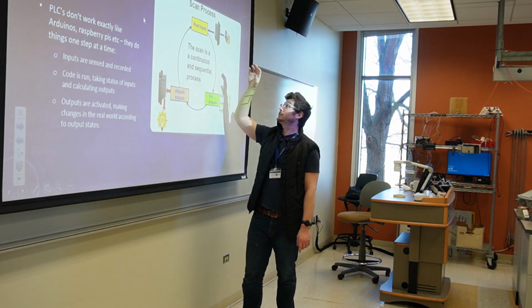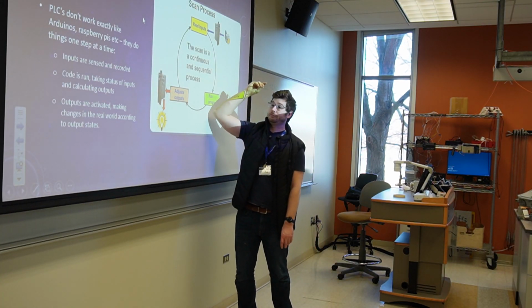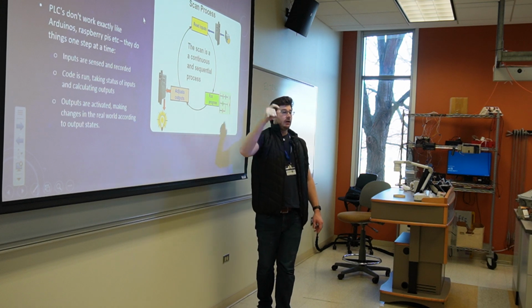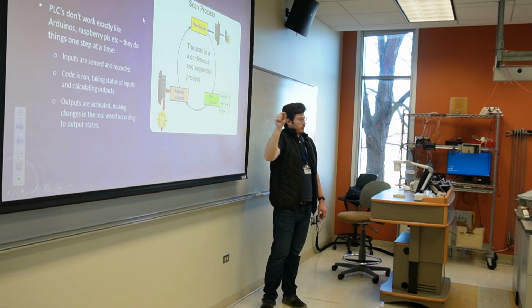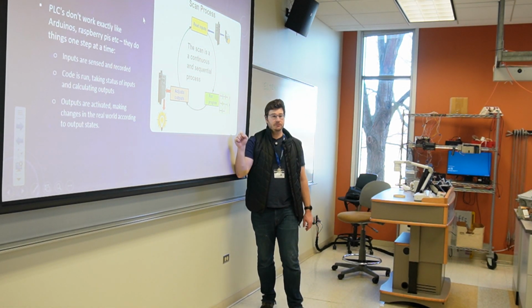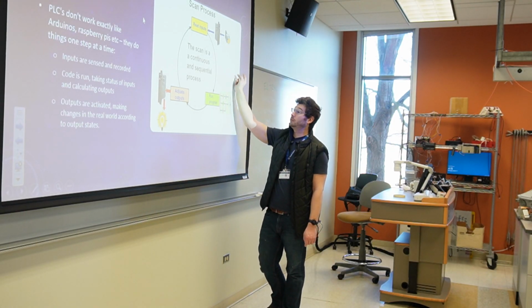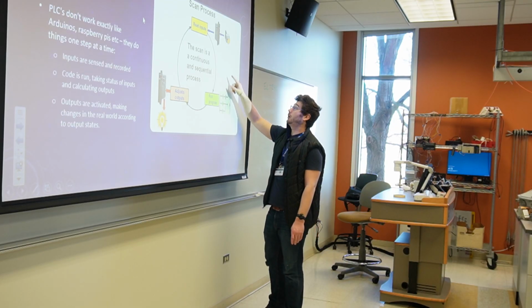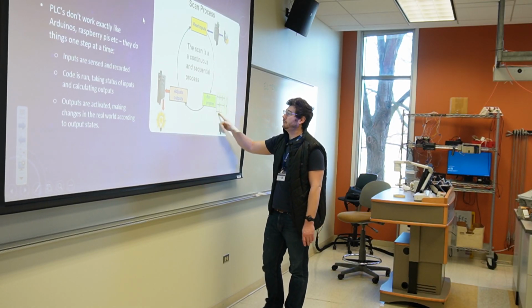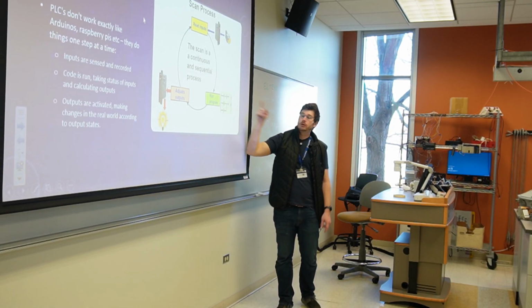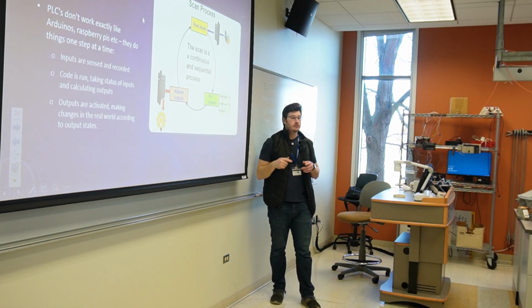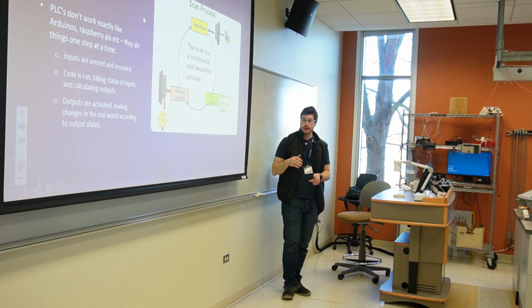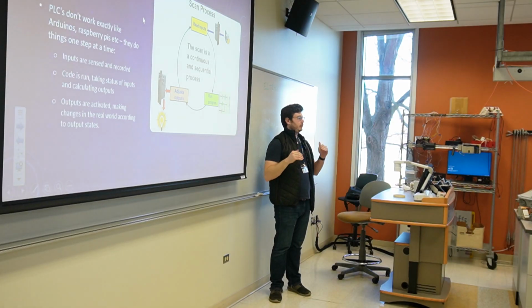Okay, so what happens is that the PLC will kind of freeze time. It'll go snap. What are all of my inputs at this current instant in time? It'll read it in almost instantly from I1 through I8, and it'll save that record. And then it'll pass that record, what are all of my inputs at this instant in time, to the program. And then it'll run calculations on those inputs. So that's when we'll kind of go line by line, rung by rung for our ladder diagram.